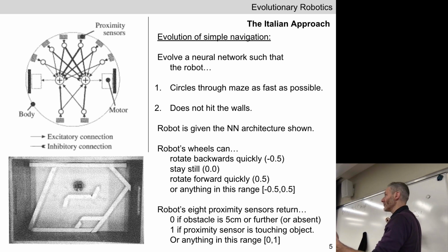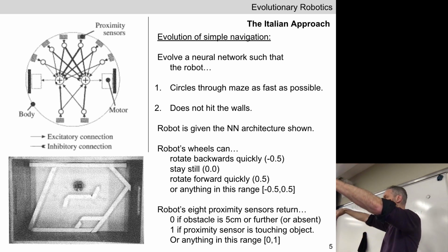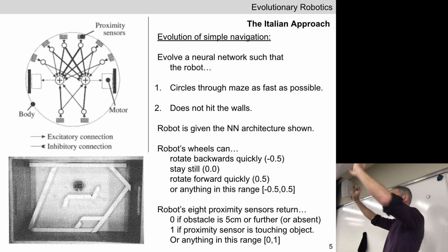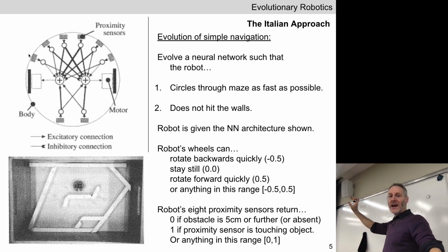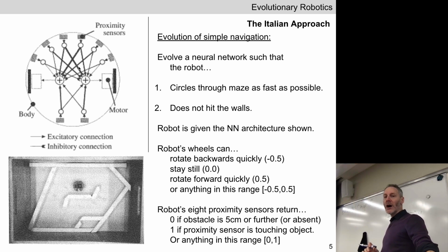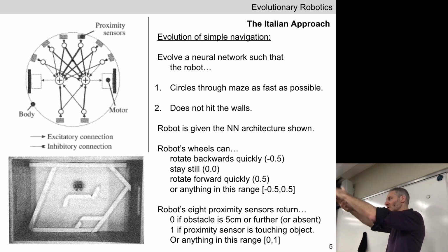Let's imagine we're running the hill climber on the set of synaptic weights. So we have one set of synaptic weights. We drop it into the Khepera. The Khepera kind of jiggles in place. And whatever else it does, there's a relatively small difference in the angular velocity of the two wheels. The hill climber takes that single vector of synaptic weights, makes a copy of those synaptic weights to make the child genotype, and when it copies the parent to create the child, it makes a slight change to one or a couple of the synaptic weights. So now the child is all those child synaptic weights.